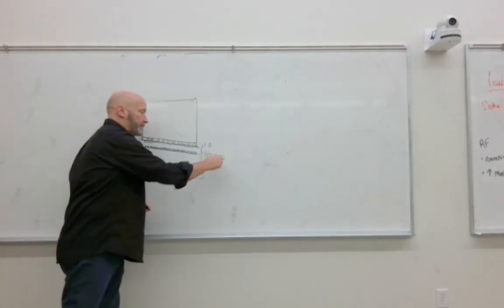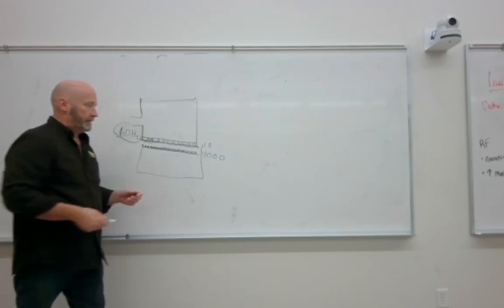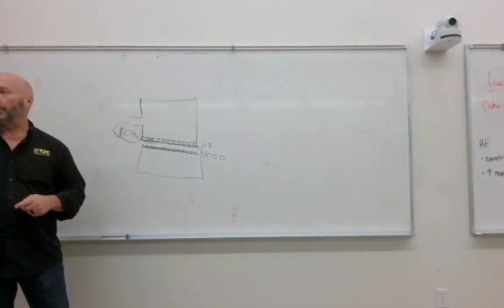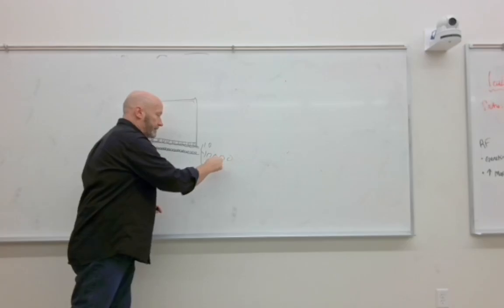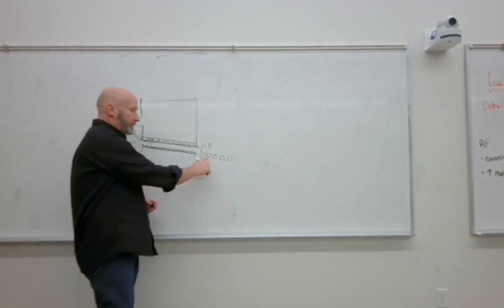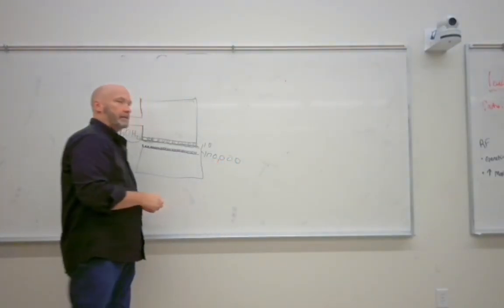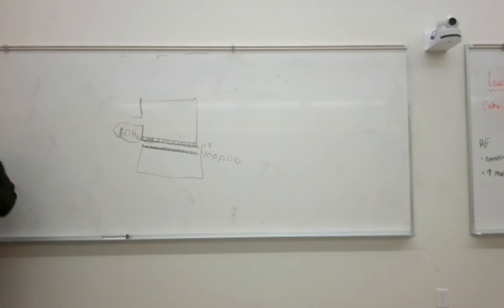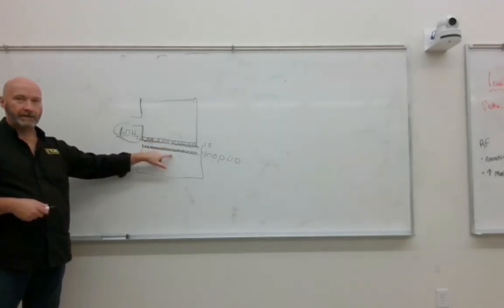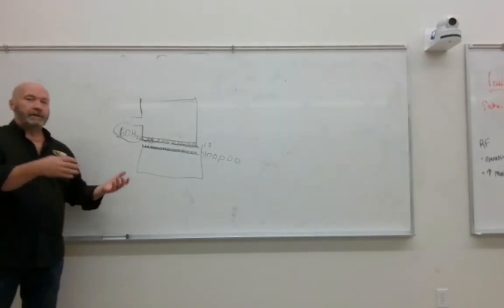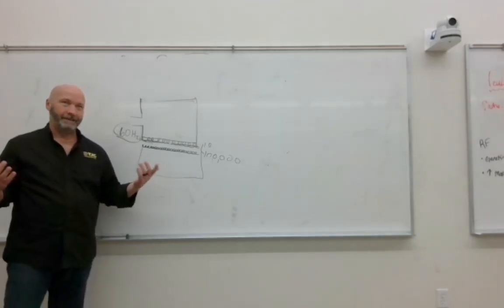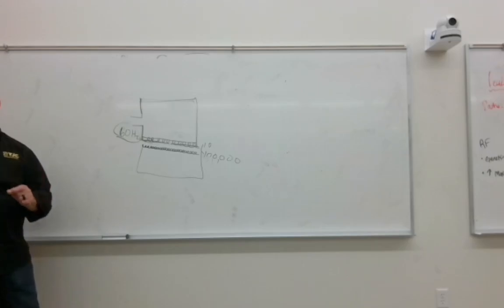If I had 10 to 1,000, that would mean that my voltage would go up by 100, right? And if I had 10,000, 1,000, yeah. And if I had 100,000, that'd be 10,000. Okay, so it's a direct relationship. If I only had 10 coils here and 10 coils there, I accomplished nothing effective. So input voltage and output voltage are going to be identical, give or take such a small amount of loss that for our purposes it doesn't matter.